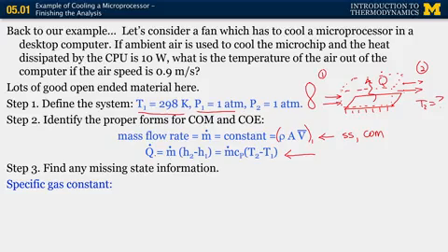And we solved, again, using a steady state assumption. We assumed that there was no work transfer in the system, which is a good assumption. There's no electrical energy, there's no shafts, no expansion or compression. And again, those are all assumptions that are linked to our definition of the system. So we want to choose our system wisely. For example, we chose our fictional volume as having a fixed volume, right? This little air rectangle here, we assume has fixed volume, and that way we don't have to worry about expansion or compression work.